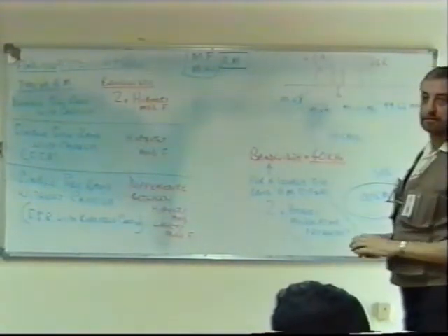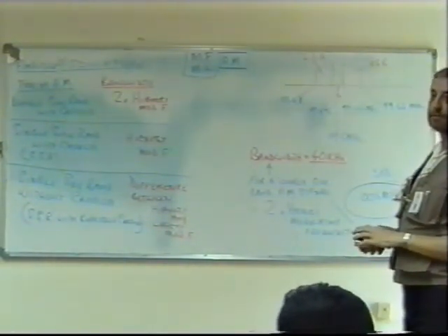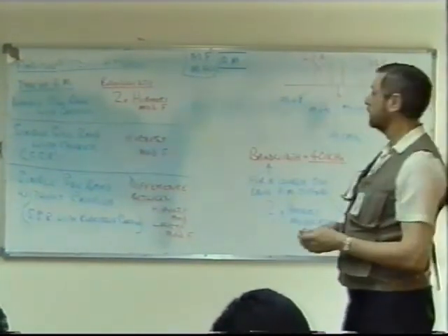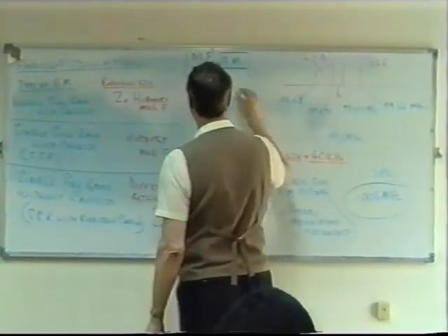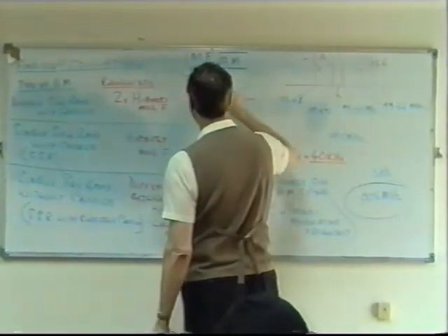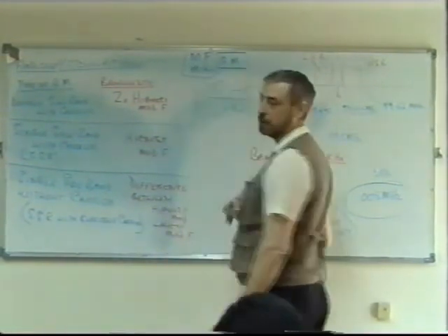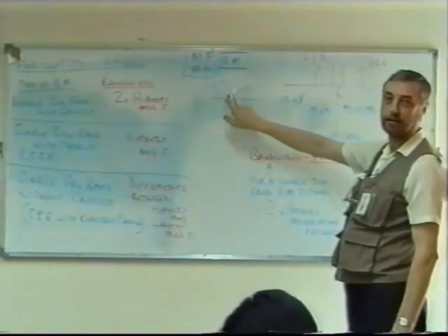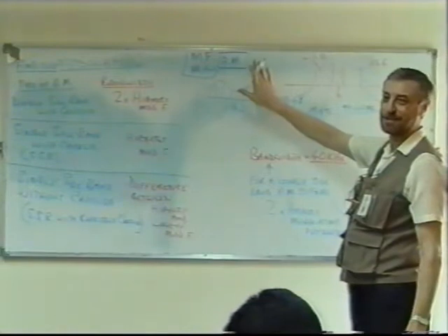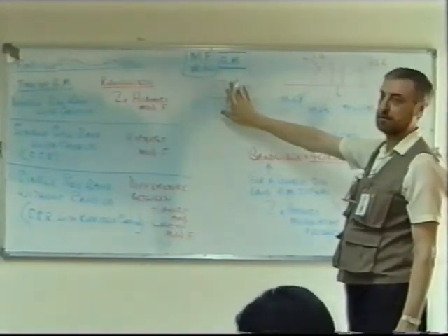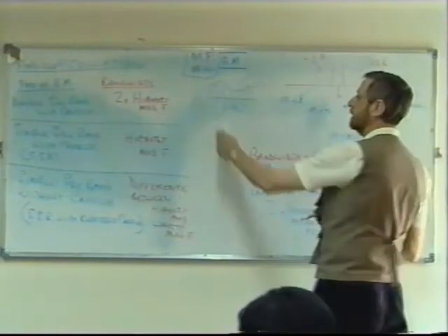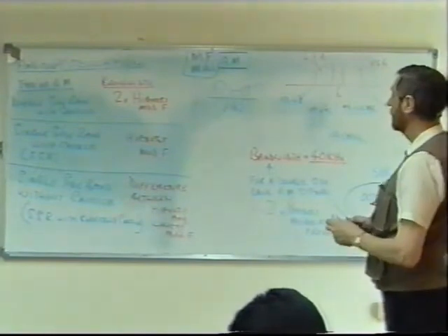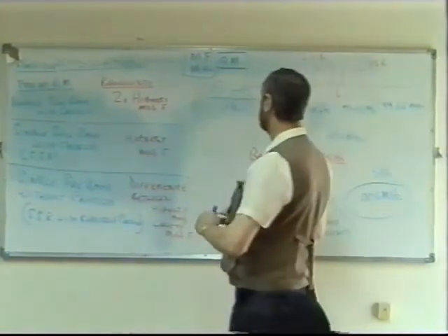You're transmitting that frequency, but there's no signal. No, there is. A lot of people get confused with this. They think about the modulation, and they think, okay, now I'm going to remove the carrier, and if you remove the carrier, the whole thing collapses. But in actual practice, that doesn't happen. All that happens is the shape of this signal changes. It's no longer an envelope modulation. It looks a little bit like this.